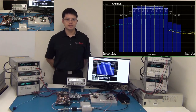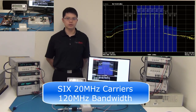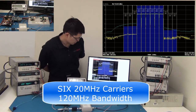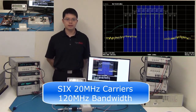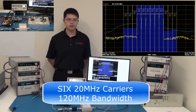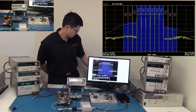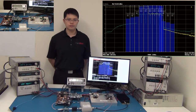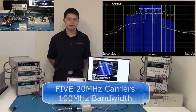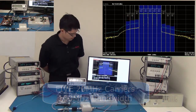The next waveform consists of 6 20 MHz component carriers to occupy a total instantaneous bandwidth of 120 MHz. As you can see, the moment we enable the linearizer, we can quickly achieve 50 dBc or better. The third waveform consists of 5 component carriers which occupies a total transmission bandwidth of 100 MHz.